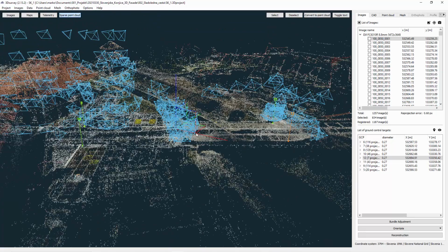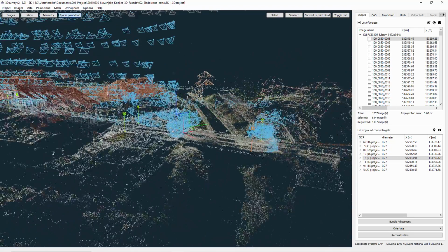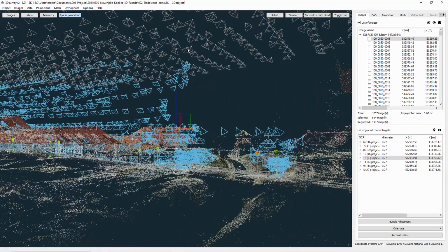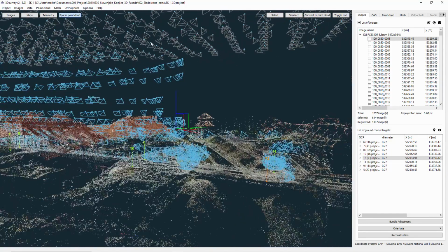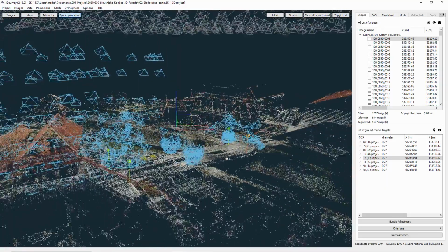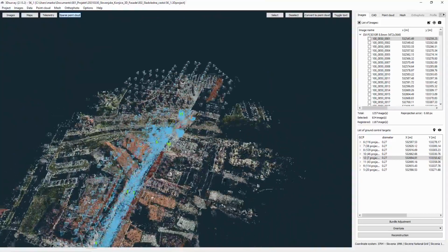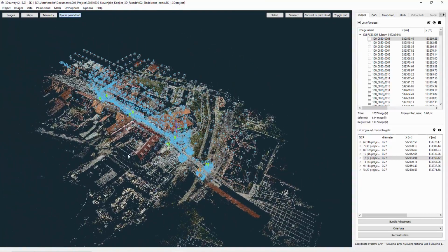Manually I hold the drone again in my hand and trigger cameras. But the important thing is you need to connect those two heights in between. So don't go from 35 meters straight to 2 meters. You need in between 20, 10 meters, 5 meters, and so on. And if you do this successfully, you get such a nice result of the bundle adjustment.